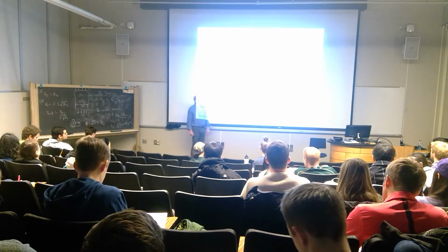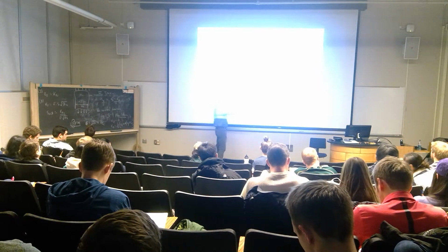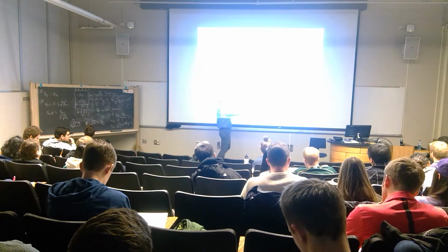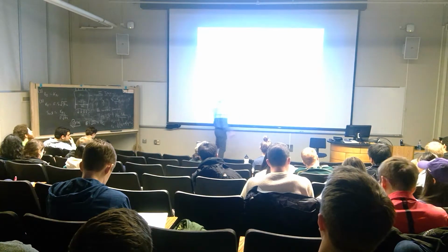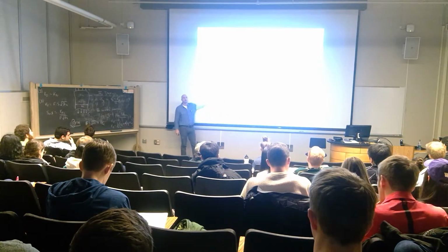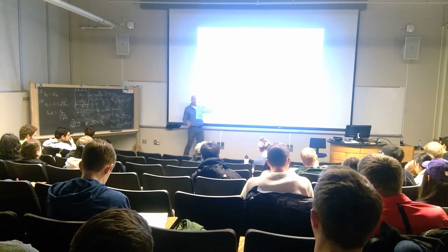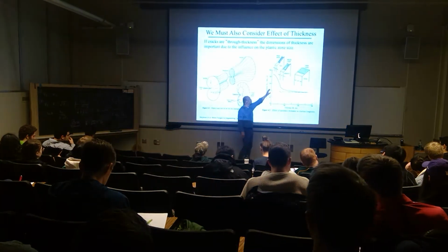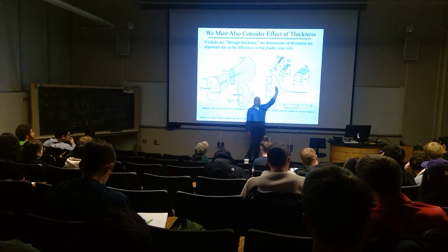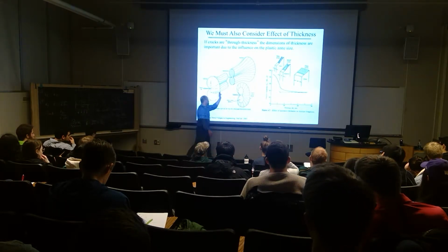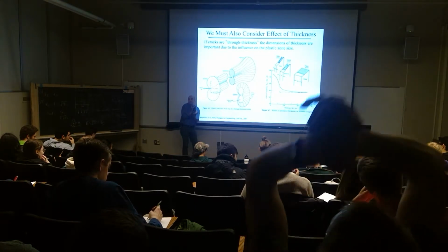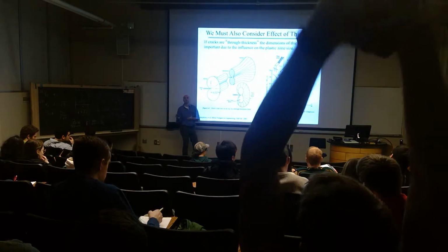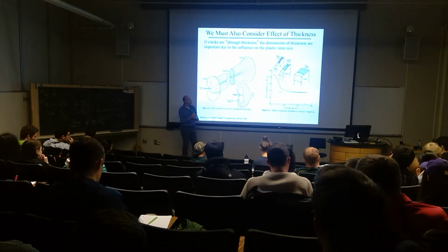It means that if we have very thin structures, then we don't have enough thickness in the interior for a plane strain condition to develop. And then we find yielding plays a much larger role in the behavior of that structure. The material will act like it has a much larger resistance to fracture because yielding tends to occur near the crack tip. That starts to ovalize the crack tip and changes its actual geometry. It reduces the stress intensity to the stress concentration.